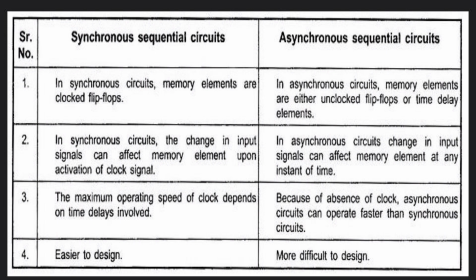Asynchronous sequential circuits: in asynchronous circuits, memory elements are either unclocked flip-flops or time delay elements. In asynchronous circuits, a change in input signals can affect the memory element at any instant of time. Because of the absence of a clock, asynchronous circuits can operate faster than synchronous circuits, but are more difficult to design.